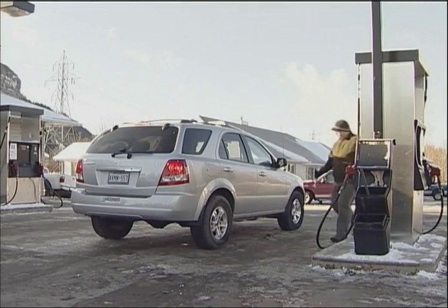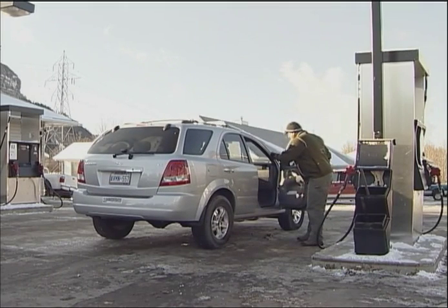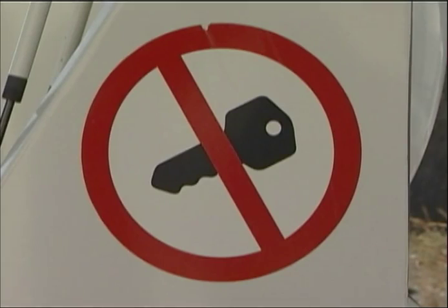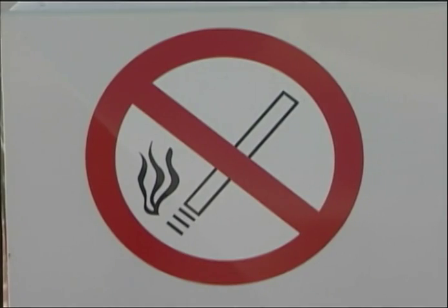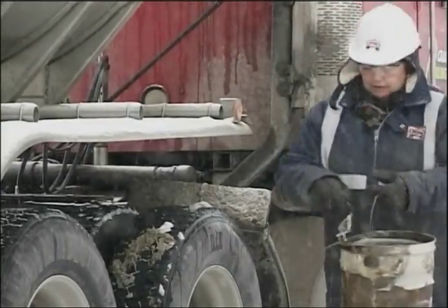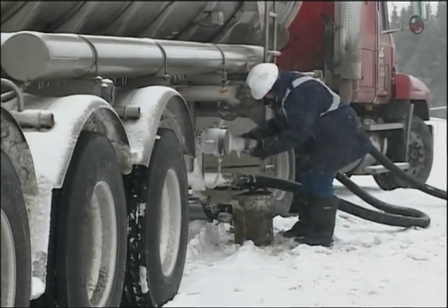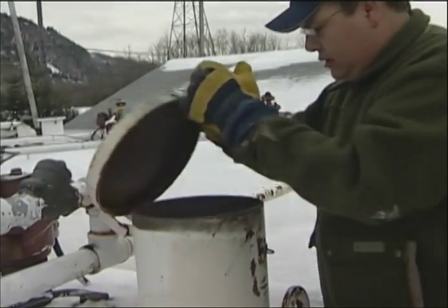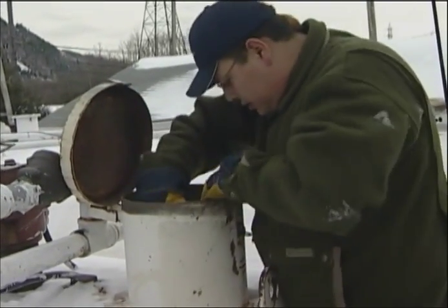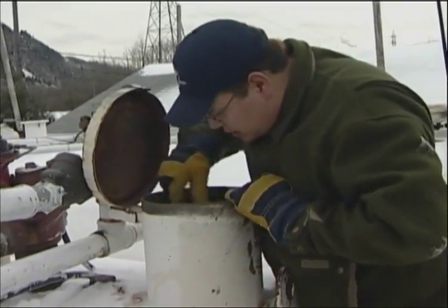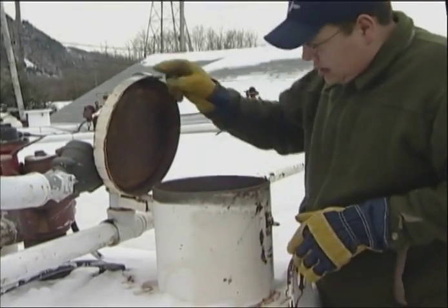Never allow a vehicle with a gasoline engine to be running at fuel site. Engine must be turned off. Smoking near or at fuel site is strictly forbidden. Always wear clothing that covers you well, such as boots and gloves. Avoid wearing nylon clothing, pants, or jackets, as this type of clothing generates static electricity which can cause a spark.